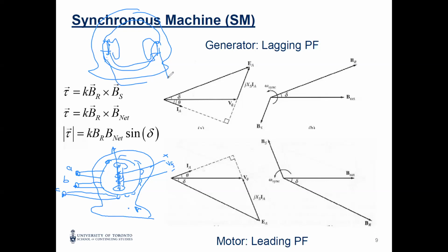Okay. This is the field winding and terminals. And then we had the rotor. Inside the rotor, we have the conductors, and then we have the commutator. We connected the commutator brushes, and then we have our DC terminals. The armature for the DC machine is in the rotor, and the field is in the stator.